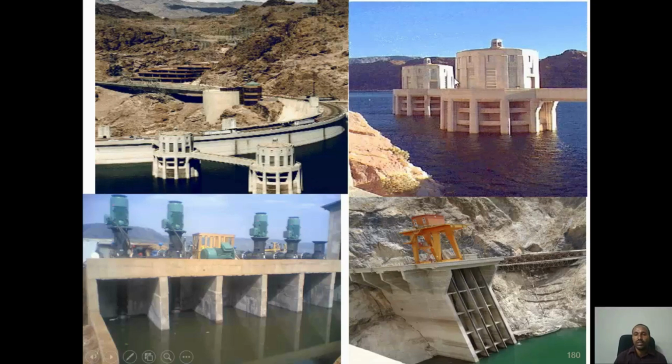This is also similar, you can see. And this is a pump, just for pumping. This is also an intake structure with pumping. And this is an intake with trash rack. So just to block floating debris, you provide grids and also reinforcement bars, wire mesh. Then debris and other trash will not enter the power canal or conduit.